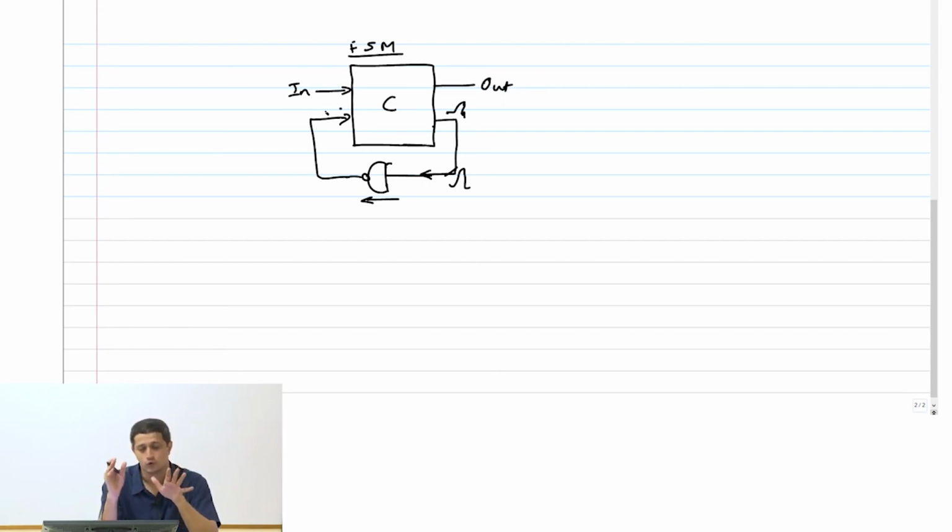The advantage with using something like a flip-flop is I can now get the delay to be actually my clock period. I can define how much delay I want, and make my system work at different clock frequencies. Here, there is only one clock frequency at which the system can work, where you make sure that delay matches over all process corners and all that, then the system will still work reasonably. But there is only one delay and one clock frequency at which it can work, right?